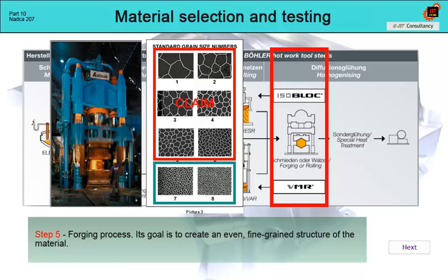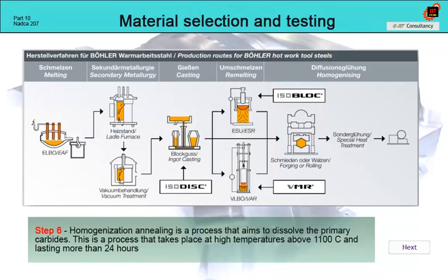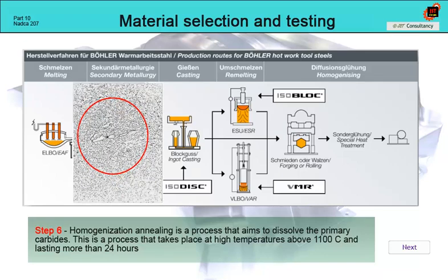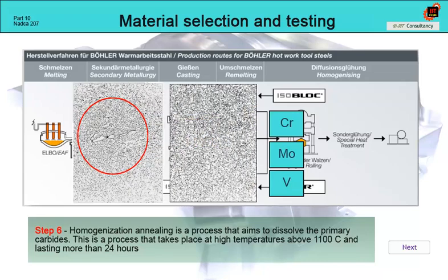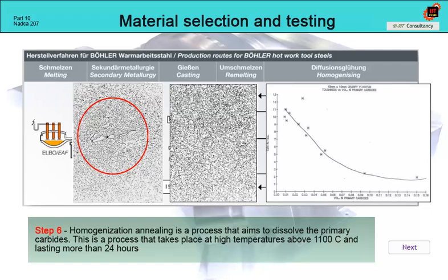or after heat treatment. One of the problems that material from the primary manufacturing process has to deal with is the size and distribution of the primary carbides. These are carbides of various alloying elements, such as chromium, molybdenum, vanadium, which are not dissolved in the matrix, and whose size is greater than 5 microns. These primary carbides are part of the purchased condition and significantly affect the impact strength of the material. The less dissolved and the larger they are, the lower the impact strength. This connection is clearly proven, and the steel supplier must be able to treat it.